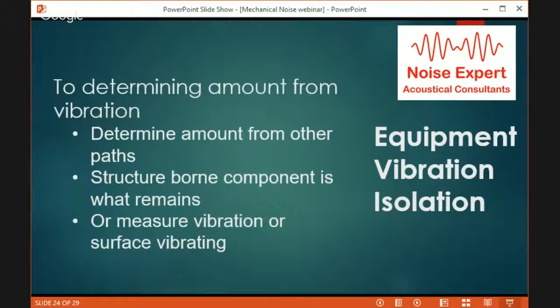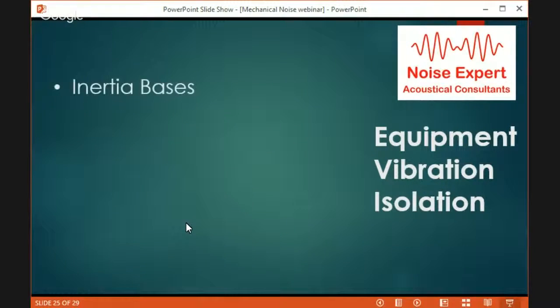Again, it gets a little bit complicated because if it's radiated noise, that's converting into vibration and then radiating on the other side. So at least it would eliminate looking at the duct-borne or breakout noise. You could just narrow it down to the radiated and vibration and see how that looks. And the more information, the better. And if you're in the design phase, that's your only option.